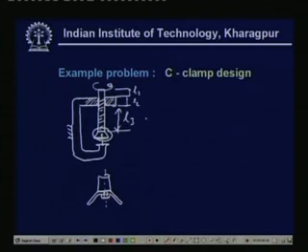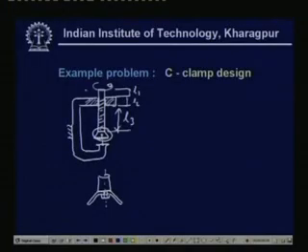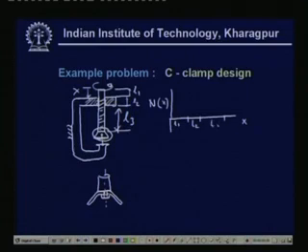Now, there will be several kinds of stresses. First of all, if we designate x from this distance, then there will be the compressive stress. The compressive stress distribution is somewhat like this, it is the Nx, that is the normal force, and here are these distances L1, L2 and L3.